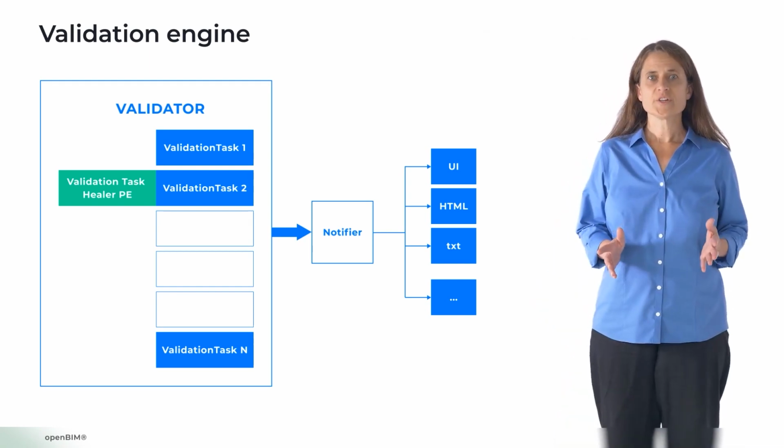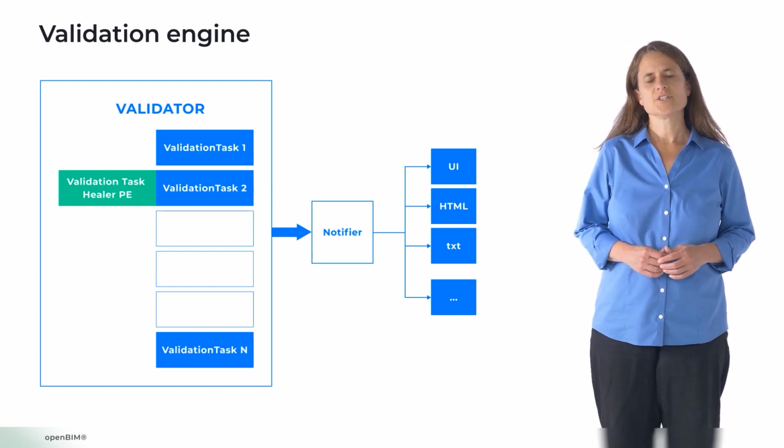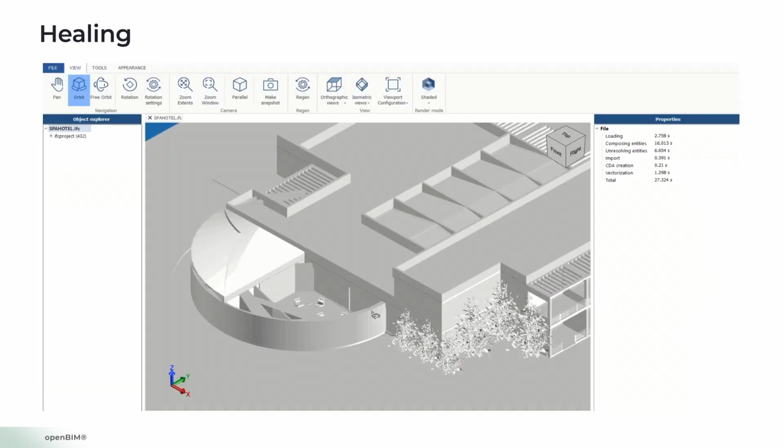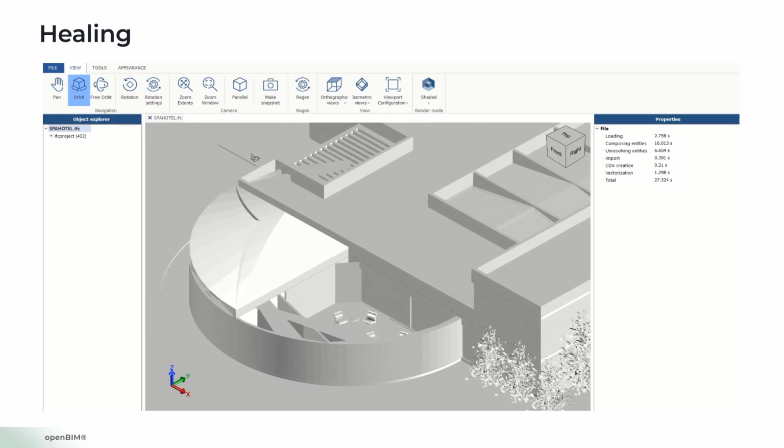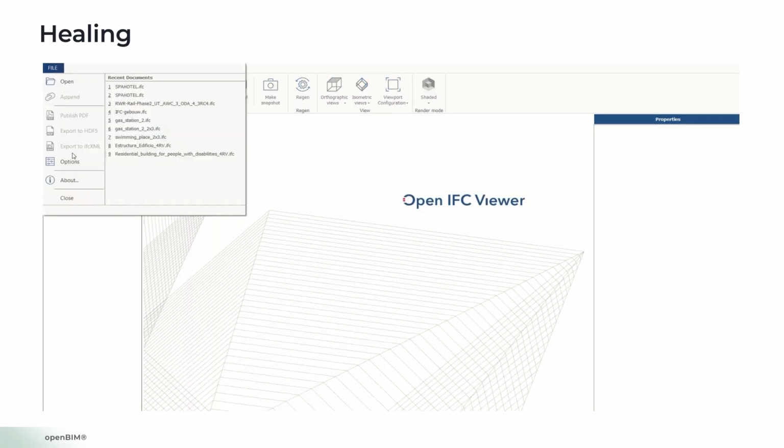This demo shows loading a file with and without validation and healing. The file was opened with validate and heal turned off, and it has a significant error. It doesn't have a plane angle unit assigned to the IFC project. That's why we have a lot of gaps in the visualization. It has incorrectly drawn some circular-based elements, such as walls and parts of roofs.